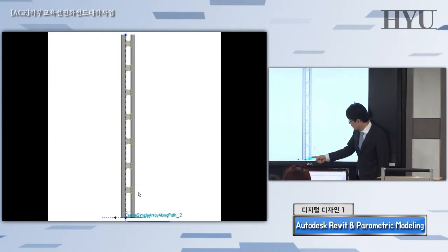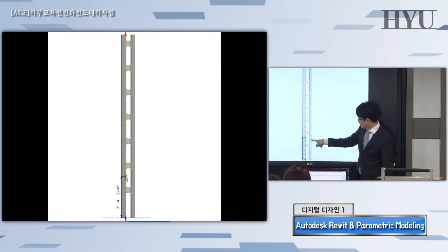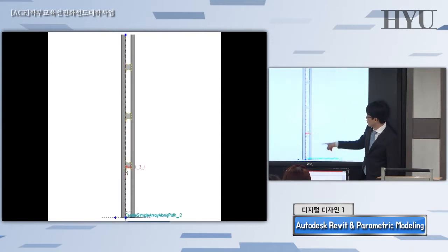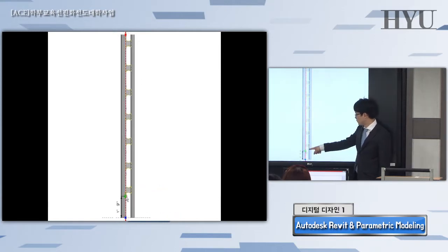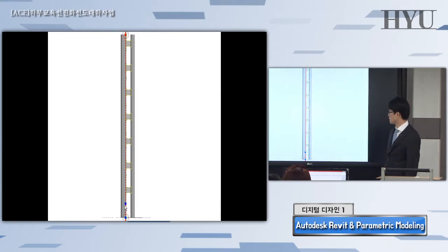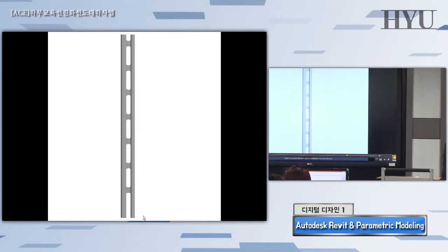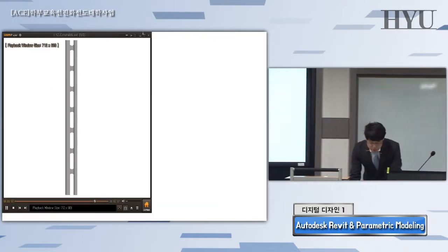And if you click this one, the height and the ratio are going to be measured by using this control point, the green point. If we change the distance, the gap is auto updated, but in this case, in terms of structure, it's not good, so it's not possible. But if we make some narrow distance, it auto updates, the same distance, simply because that's the parameter. This is the first example.